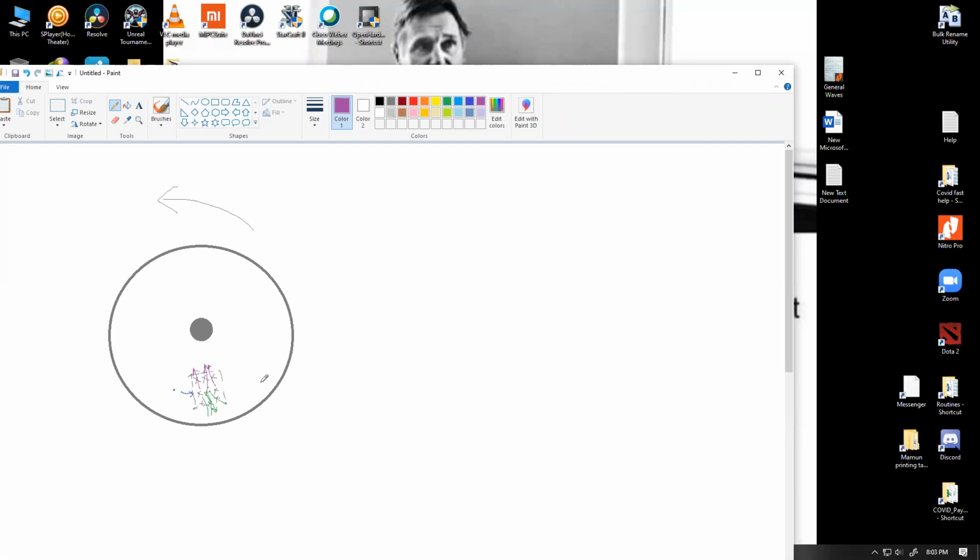This vertical current is existing exclusively because the magnetic field is there, which is applying some force on the moving electrons as they are trying to pass through that magnetic field. And as the magnetic field is pushing onto those electrons, they are trying to move because of the effect of the magnetic field. Because of that, they are producing a current. So what's going to happen? Electrons are going to try to rush out through the bottom. So conventional current is going to be produced over here. Well, obviously there is not a single electron on the metal disk. There are a lot of electrons. So we're going to have a pretty high amount of current that will be flowing out of this space.